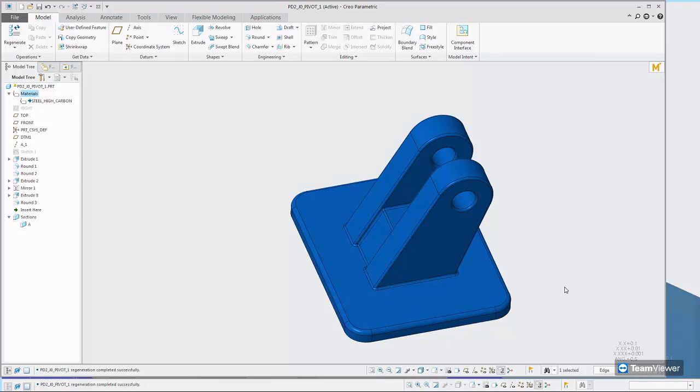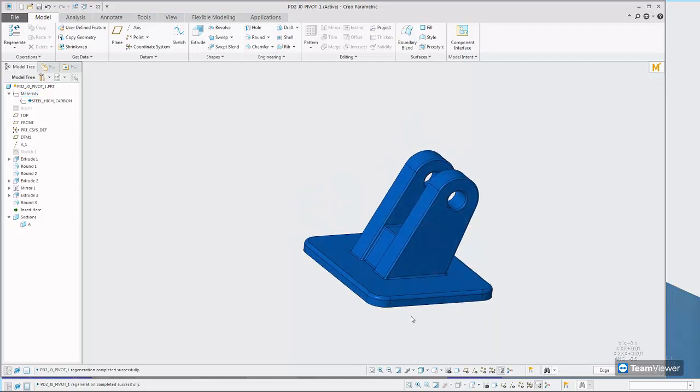Another nice feature available within Creo is the ability to document your design intent using MathCAD. Now I'm sure some of you have heard of it or even used it out there. One of the things that not many people realise is how it can be embedded within your actual Creo model itself. Some of you may have noticed that I have this MathCAD icon at the top. This is telling me that some dimensions of this particular model are driven by a MathCAD worksheet. So let's see how that is actually working in the background.